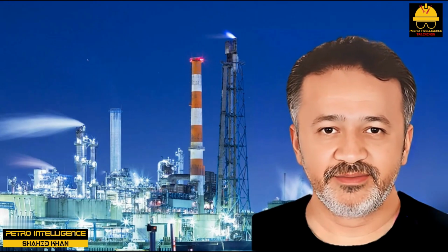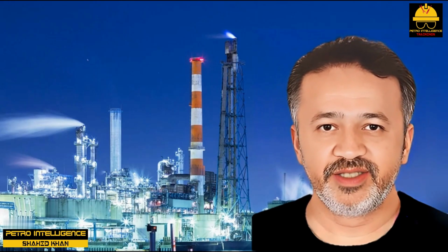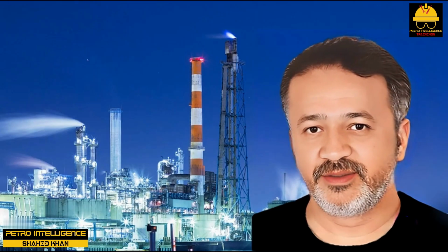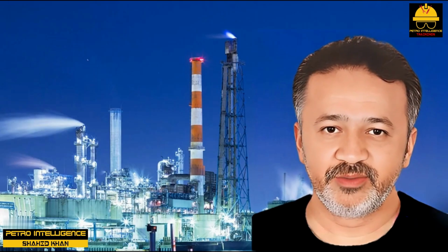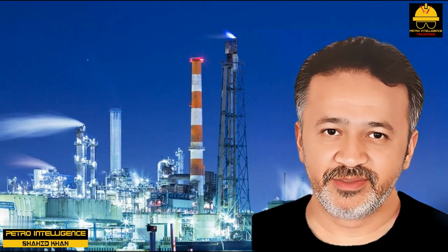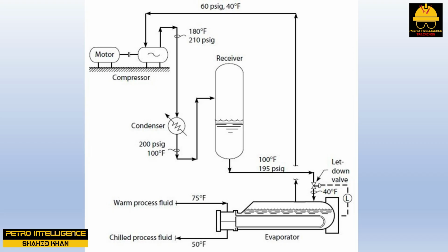Overcoming speed limits. While the actual cubic feet of refrigerant vapor to the compressor may be limited by the compressor's speed, we can still overcome this bottleneck. The trick is to make the refrigerant lighter or more volatile. A lighter refrigerant will allow the evaporator, shown in picture, to operate at a higher pressure or a lower temperature.